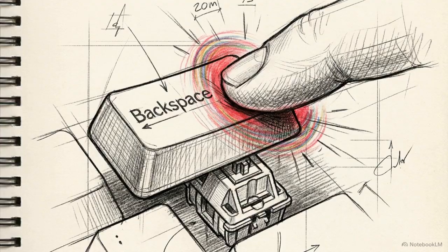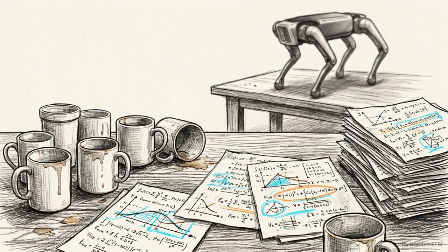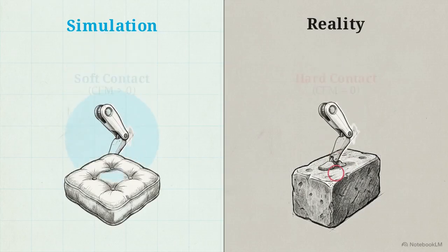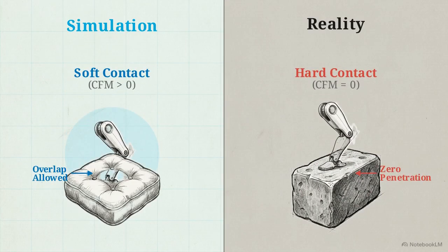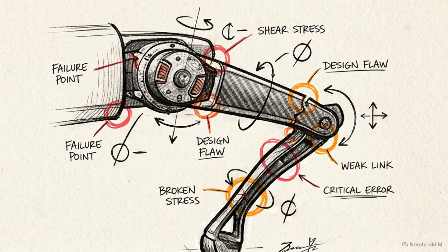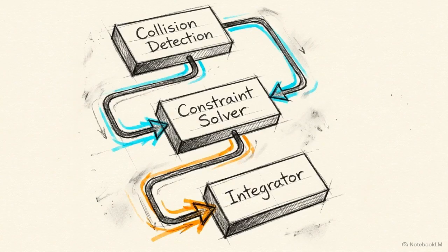Your first instinct is usually to blame the controller. You go back to your desk, assume your tuning was slightly off, and start adjusting your math to account for the physical hardware. If the simulation allows for physical shortcuts that don't exist in reality, a controller that looks perfect on screen is doomed to fail. To solve this, we have to look at how the virtual physics engine approximates the physical world.